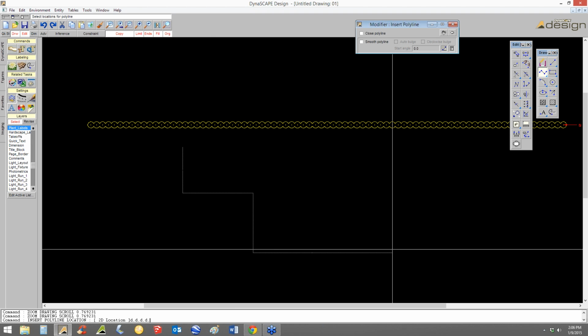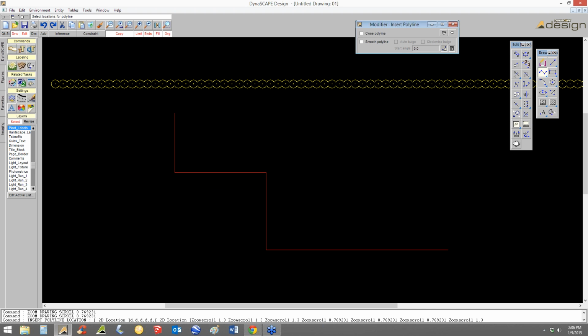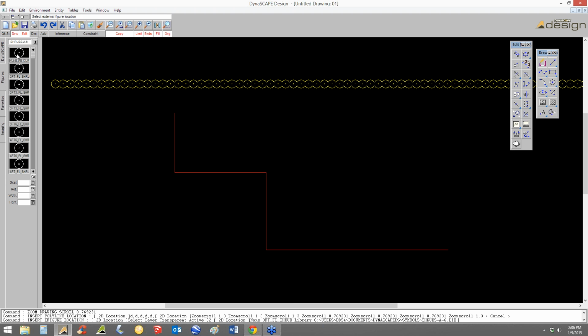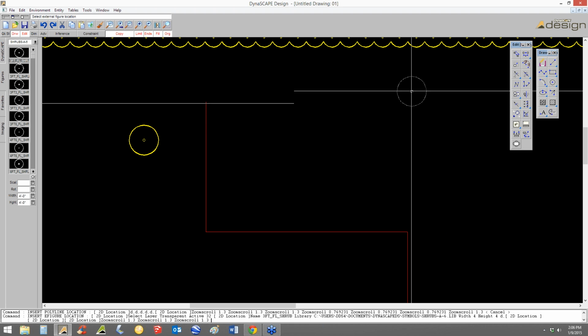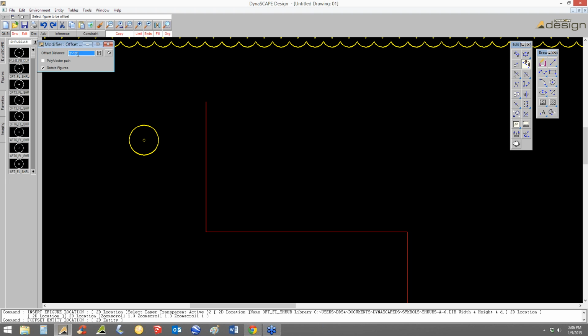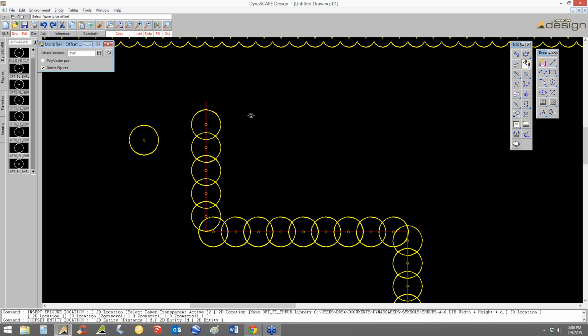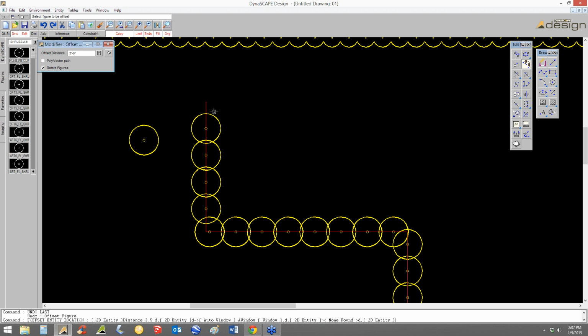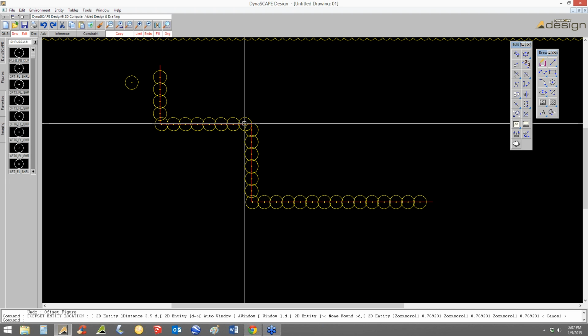So pretty quick. It works along any line. So if I wanted to do a boxwood hedge along that line, I would do the same thing. I would go grab my boxwoods. Let's do them 4 foot. Sit that there. Go grab the tool, and let's set those apart like 3 feet. Click the boxwood with the left click. Click this with the left click. So those are obviously way too close. So then I'm just going to back that out, and I'm going to go maybe 3.5 feet. Offset. Click once. Click that. That looks much better. Pretty easy way to do that.